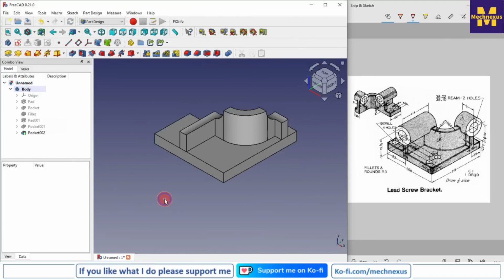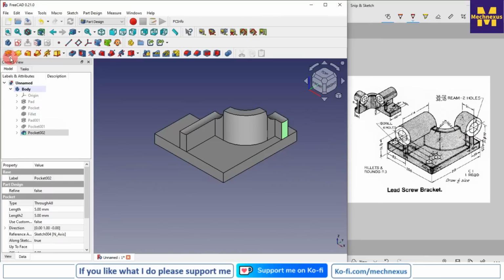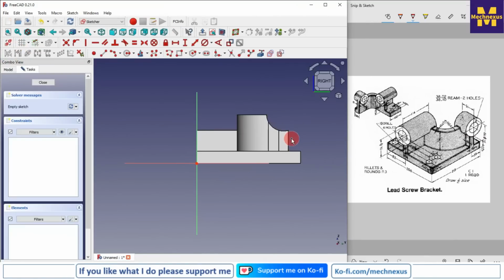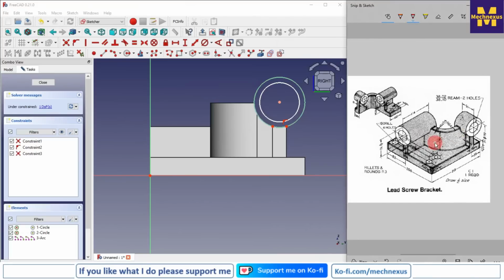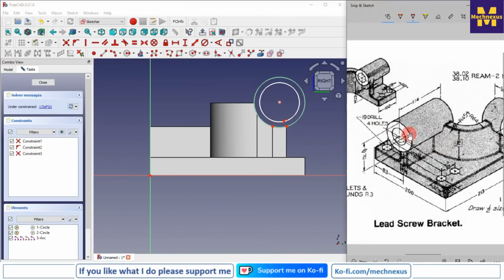Now we will create this boss now. So for this we will again select this face and create a sketch, and here we have already made the cut feature, so we will project the geometry. So inner bore we will see in a drawing, as drawing is not much more clear.